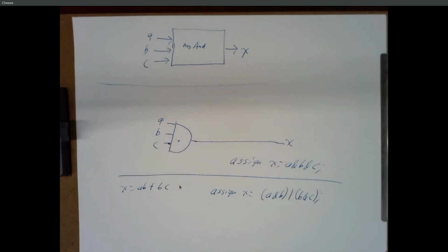But with physical hardware, I can go through more software and say, take this Verilog output and actually program this chip to implement this circuit that I've described. I can say, let's use pin 17 for A and pin 39 for B and pin 64 for C and pin 12 for X. And I program this chip, and now I can take this chip off and connect it to a breadboard, and if I put 3 switches onto whatever those 3 pins were that I named, and an LED on pin 12 for the output, it's a 3-input AND gate, right? Or, you know, AB or BC, or whatever I wrote the Verilog for. So it's customizable hardware.